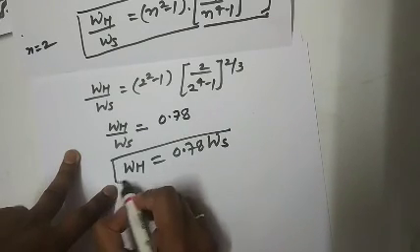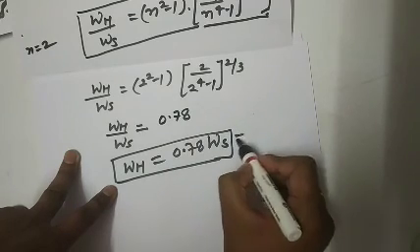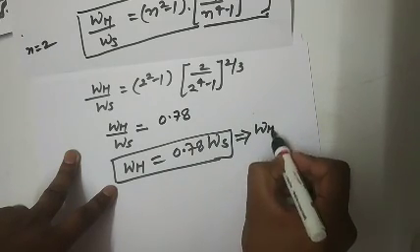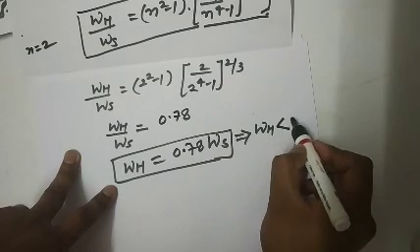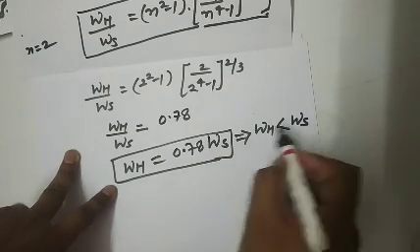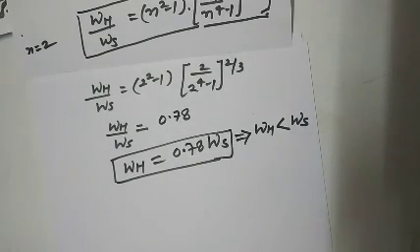So this expression suggests that the weight of hollow section is less than the weight of solid section for the given condition. It will be economical to replace the solid shaft by this hollow shaft, right? By strength hollow shaft is economical, by weight hollow shaft is economical, so it is always preferred to use hollow shaft.